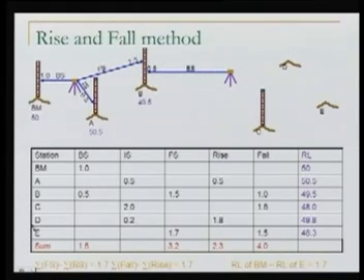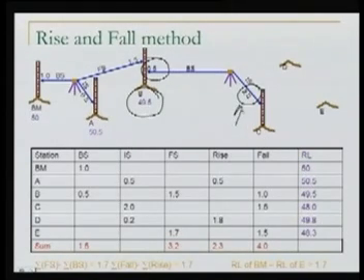Next, I take my staff to C and take the intermediate sight here. So again at this point I can now compare, because I know already the RL of B. I can compare by taking this backside and this intermediate sight, whether C is higher or lower than B. Because the reading is more, C is definitely lower. So C has a fall of 1.5 meter from B. So C is lower by 1.5 meter from B.